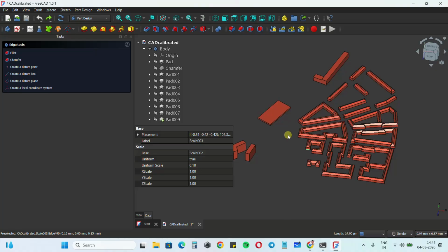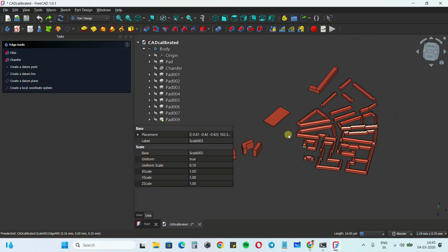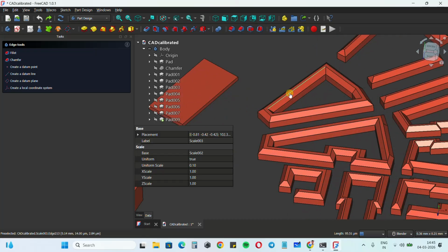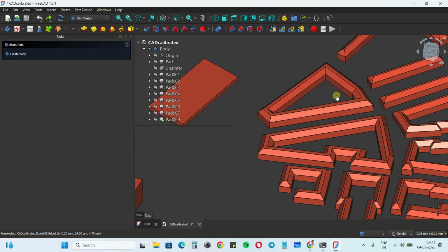There is this confusion. So when you export as an STL file, the thing with STL file is that it basically doesn't store units. So if you have modeled the geometry in millimeters, and if some particular dimension, like maybe this dimension, is 0.11 millimeter, then when you open the STL file, perhaps in OpenFOAM or ParaView, you only get the information of 0.11. So we don't know if it's millimeter or meter. By default, OpenFOAM considers all the numerics to be in SI units, so it would interpret things as in meters.